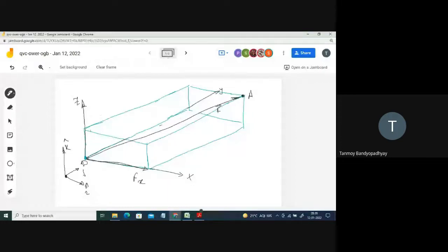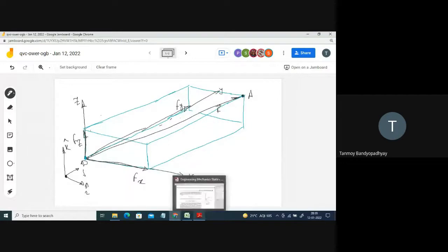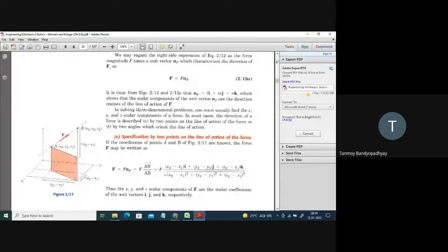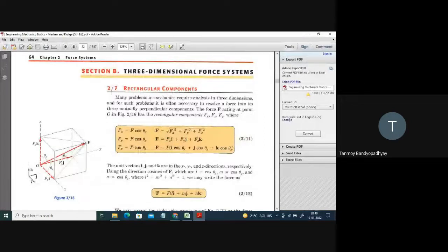Along the y directional component, মানে এই directionটা, so this will be fy. So this you are getting it as fy. Z directional component, this one you are getting it as fz. তাহলে এইভাবে you can get the three components of the force. তাহলে এইবার এই যে ইনক্লিনেশনস গুলো, so if you could see all these inclinations, মানে এই ইনক্লিনেশনস গুলো যদি জানা থাকে, so the inclination with x direction, y direction and z direction, if we know that, so সেখান থেকে we can define fx, fy and fz.